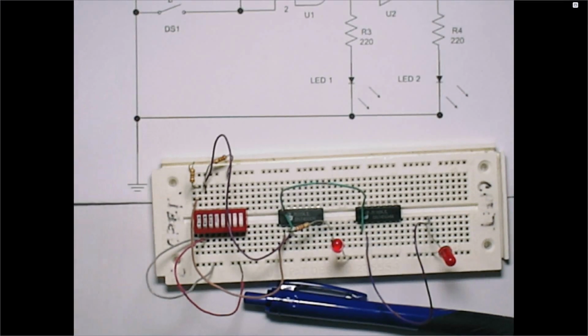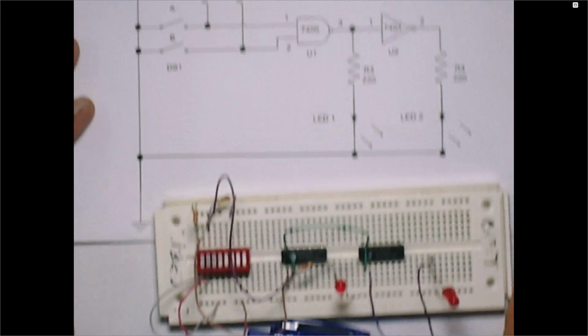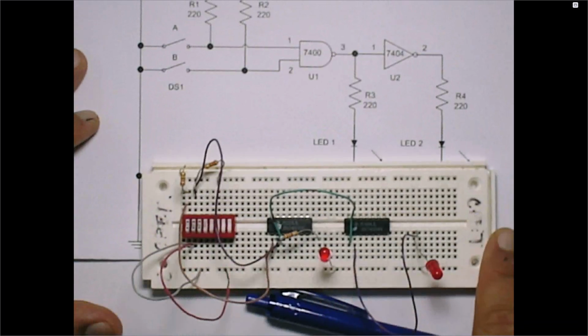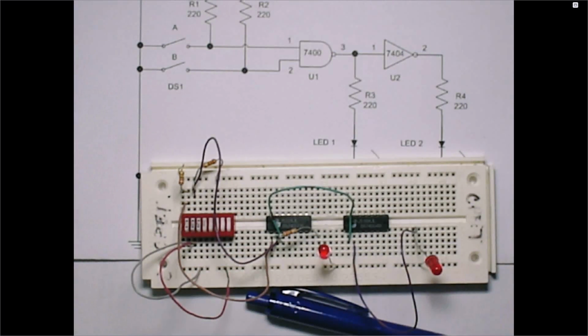Now, I'm pretty much done with this circuit following the schematic here. So all I did is I just followed the schematic and built the circuit. Now, what is still missing? Do you see anything missing here? I pretty much followed everything that we had in the schematic, but still I have something missing. What is that? Do you remember when I started talking about the IC, I said every IC has to be grounded and has to have a VCC. We have not done that yet, right?